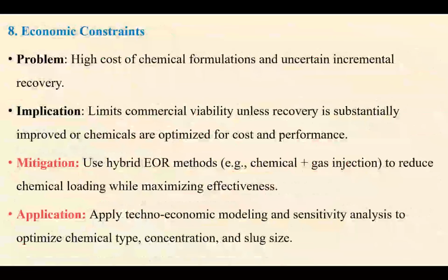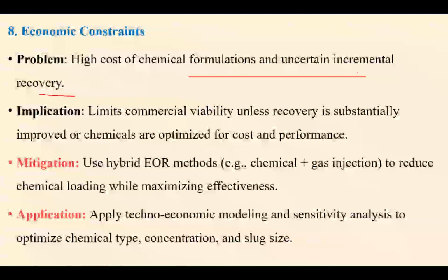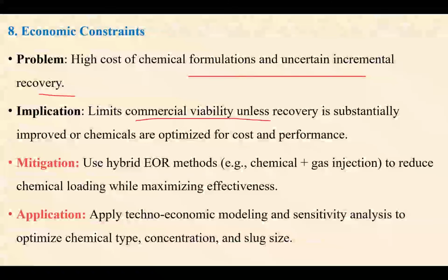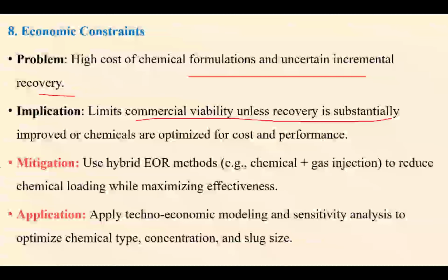Now, the economic constraint: the high cost of the chemical formulation and uncertain incremental recovery. Here, the incremental recovery by this chemical method, as tested by different studies or laboratories, is found to be much less compared to conventional reservoirs. So one thing is the high cost of the chemicals, the other is the uncertainty. So these are basically some limits. These limits control the commercial viability of the process unless the recovery is substantially high.